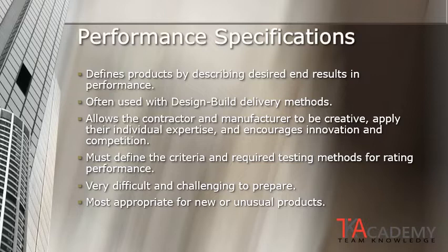It allows a contractor or manufacturer to be creative, apply their individual expertise and experience, and encourages innovation and competition in the market. In order to write this type of specification, you must define the criteria and required testing methods in order to evaluate and rate the performance. That makes it one of the more difficult and challenging types of specifications to prepare. This type of specification is most appropriate for when you are using a new or unusual product.